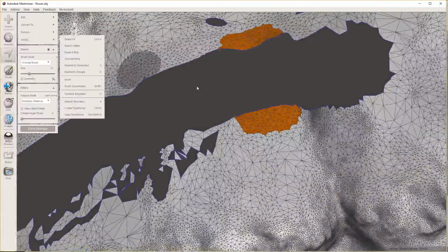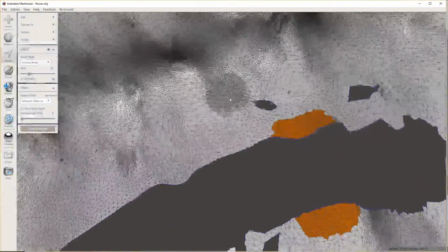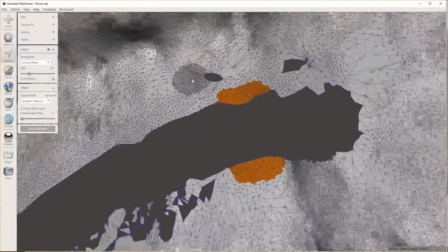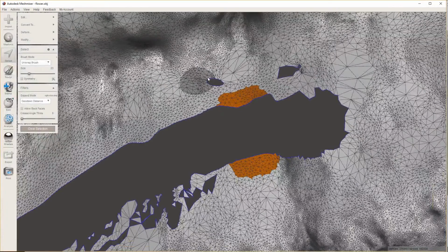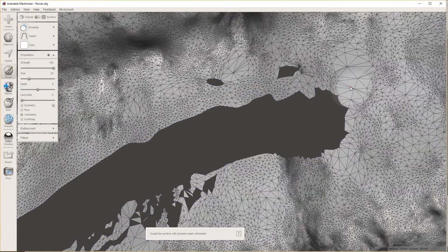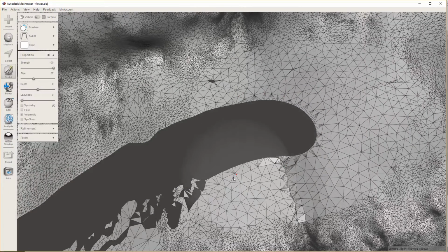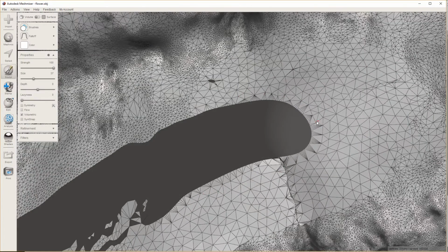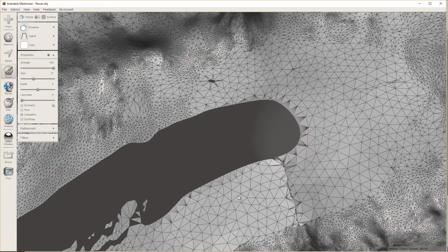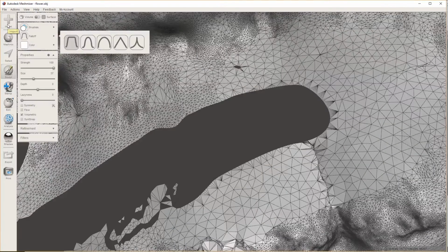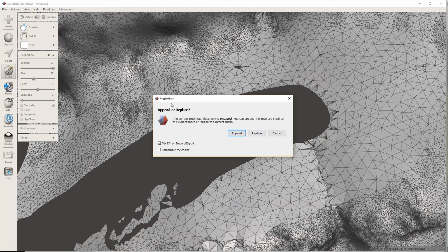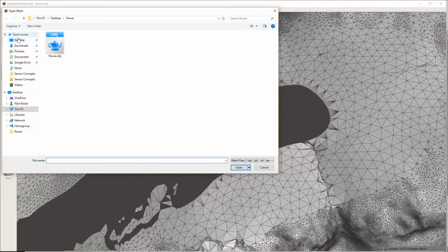So the Robust Smooth tool is really, really good. So that's just another thing. You can use the Robust Smooth tool for closing holes, so we could use it there, and for also smoothing out difficult parts of your mesh. Right, so pretty cool. So now I want to show you the last thing, which is a really awesome thing, and this is at looks like minute 23. And here's the thing that I'm very excited about. So let me go in.